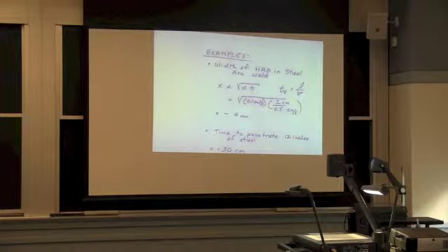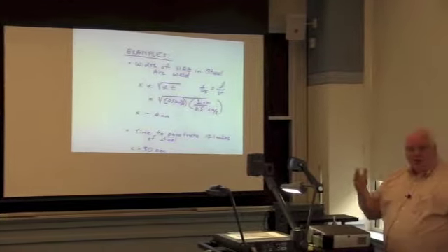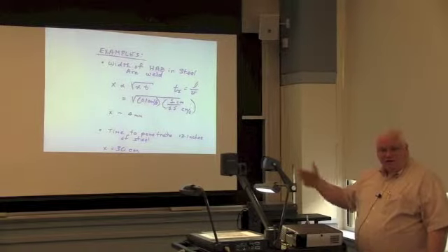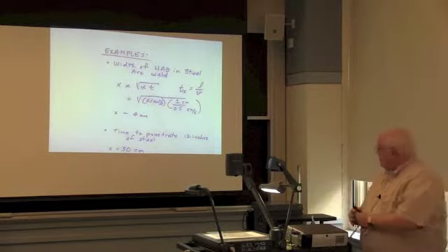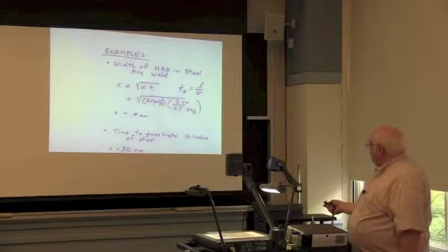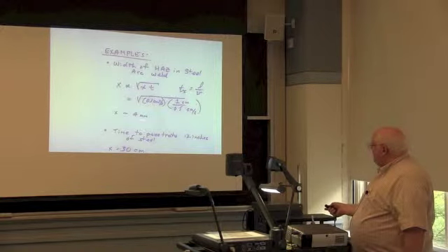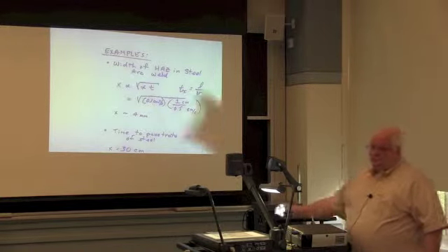So I'll pass this around. Anybody know what 4 millimeters is? It's about 3/16 of an inch, a little under, right? So look at that heat affected zone. It's about 3/16 of an inch, right? Well, there it is. If I want to know if the heat affected zone is 1 millimeter or 10 millimeters, I can go through a simple little analysis like this. All I had to do was figure out my interaction time and take Fourier's law, and I come up with a number that's reasonably close.